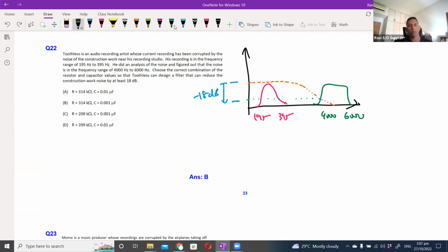If you go back to our tutorial on this, you realize that it's always the same approach. The gain is always the pass band gain minus the frequency specific gain. The pass band gain is basically the active component. If I put in an inverting or non-inverting amplifier, then I amplify the signal. If you don't have an active component, you just assume there is 0 dB, meaning you take it as it is. Then what is left is only the frequency specific gain, and that formula is fixed: whether low pass or high pass, each has its own formula.